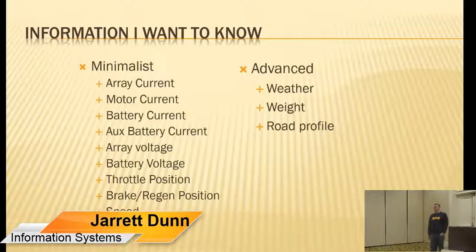So what I'm personally interested in, and this is based on my experience, is that the currents are the most important thing that you can deal with. How much current is basically equivalent to how much gas you're using. In batteries, you measure the capacity by amp hours. That is how full your tank is. You have 100 amp hours, 200 amp hours, whatever. So in order to know how much you've used, you need to know how many amps you're using. If you know how many amps you're using and how much time you have used it, you know your amp hours. So my top items are the currents.